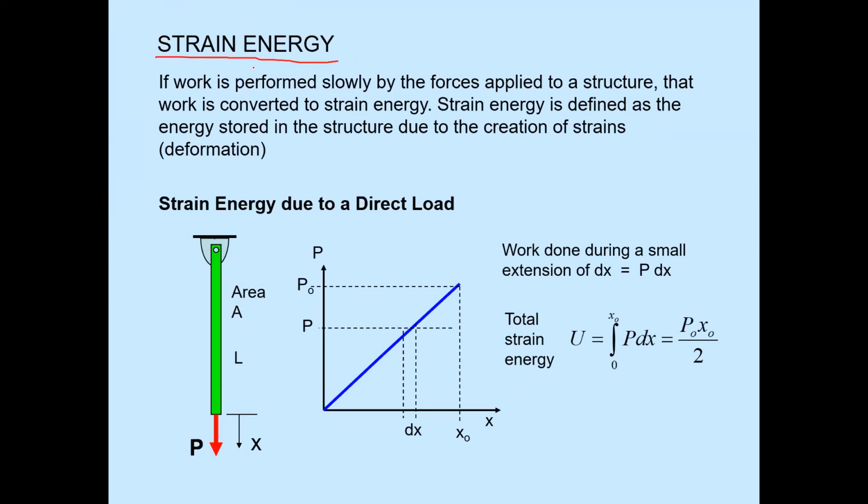If you have a good understanding of the concepts, then it is a very easy subject. So what is this saying? If work is performed slowly by the force applied to the structure, that work is converted to strain energy. It means if we apply a force P to any structure, then the work done by the force P is converted to the strain energy.